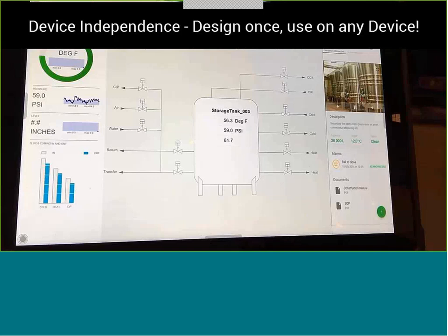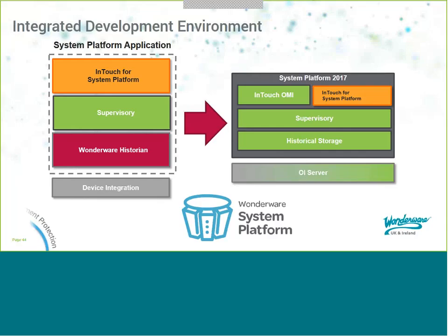In terms of the sliding panes, this is allowing for much more real estate. Typically your SCADA would have the navigation buttons always on the screen. In this case, we swipe in from the left or the right and those panes appear. And again, it's a very simple way to configure those. It isn't having to do any scripting or anything like that. You choose an option to include a sliding pane in it and choose what size you want it.